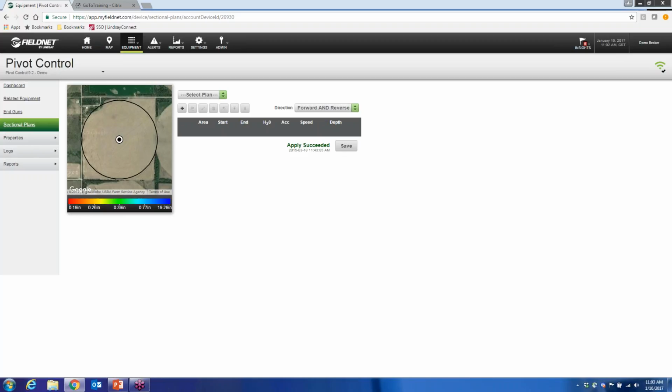As far as sending an analog signal to the pump to speed it up or slow it down itself, we just do basically a contact that opens and closes. So you'd want to adjust the rate of your machine in order to use the fertilizer pump.